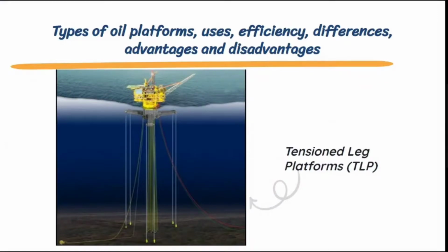The tension load is transferred to the foundation system through the tendons that make up its mooring system. The tendons are anchored to the seabed by means of a structure made from structural steel and assembled by piles.